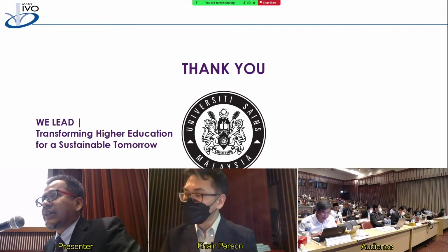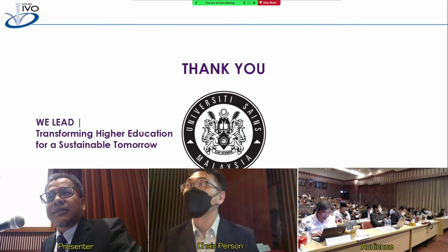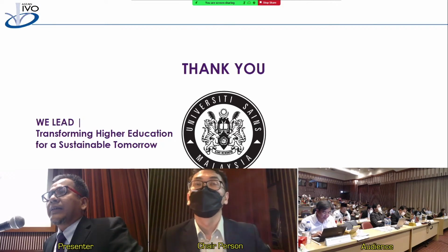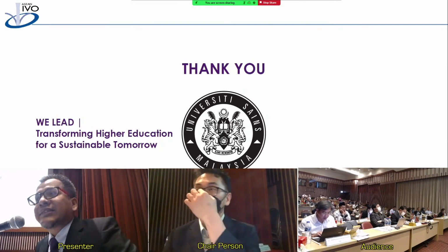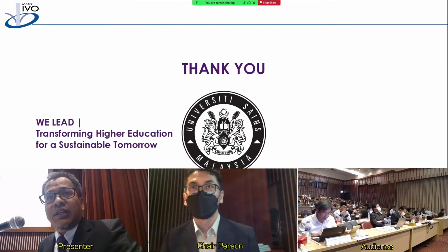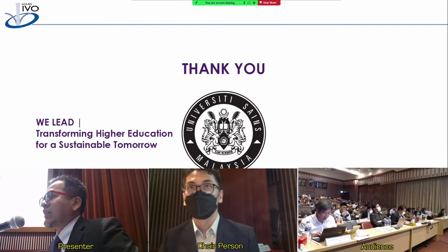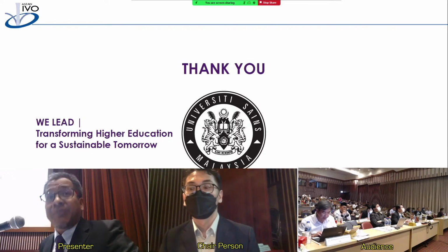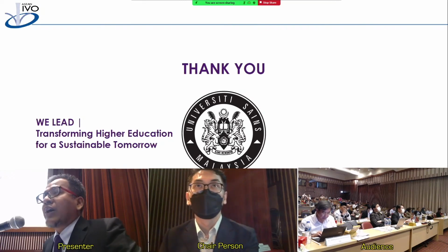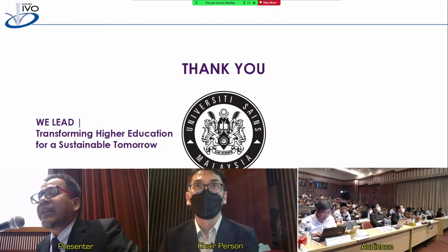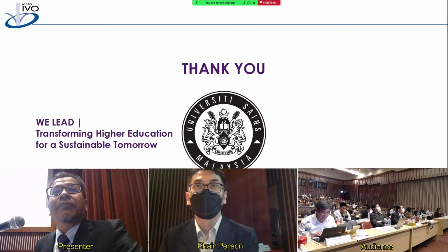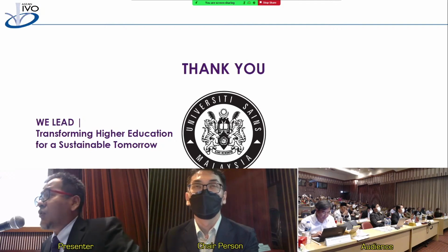But what our target here is, we want to have a system that is simple but easier to do the fabrication using a standard printed circuit board. So the uniqueness of my project is that we approach a lab on PCB, lab on printed circuit board. Then to answer your question, how possible it is to miniaturize, is it up to the nano, it still depends on the limitation of the printed circuit board fabrication technologies.